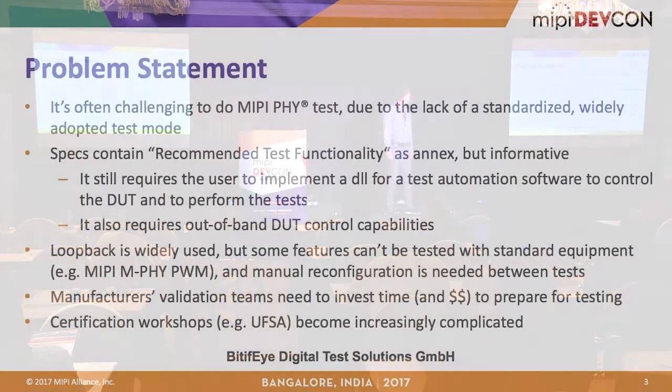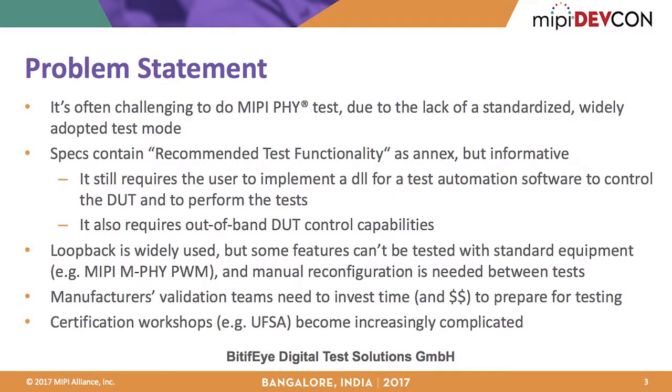So the problem is, as you can see here, that it's often challenging to do MIPI PHY tests. There is a lack of standardized and adopted test modes. The specs contain recommended test functionality, but it is rather informative, and therefore it requires the user to implement a DLL for the test automation software to control the DUT and perform the tests.